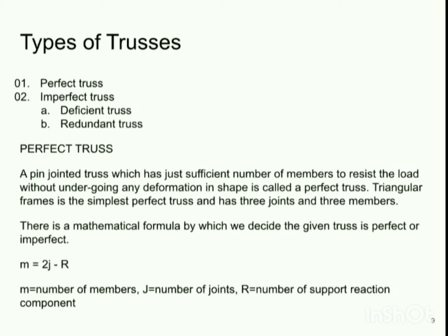So we have only three conditions of equilibrium. So for all the cases of analyzing a truss when all the forces are acting in the same plane, we have three reactions, that is the value of r will be equal to 3. Depending upon the different type of trusses having different configurations, the number of members and number of joints will change.